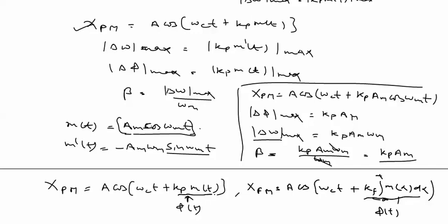For example, in an angle modulation scheme, if the modulation index halves when the modulating frequency is doubled, the scheme used is FM. If doubling the modulating frequency does not affect the modulation index, then it is PM.